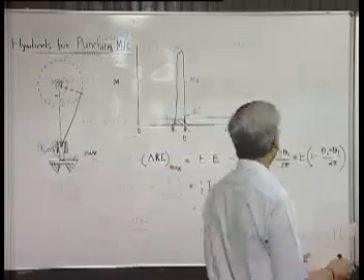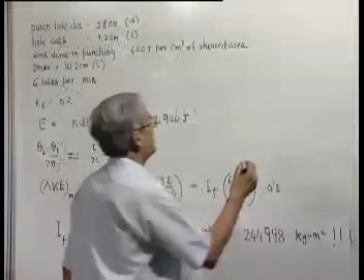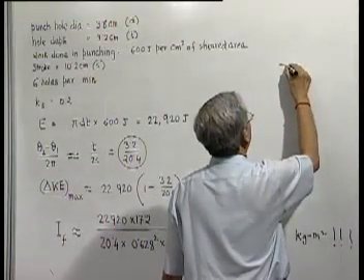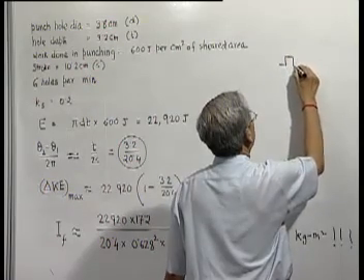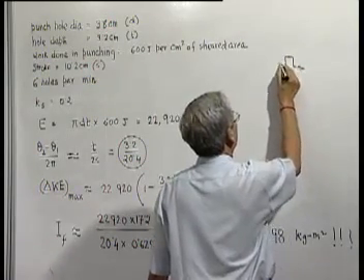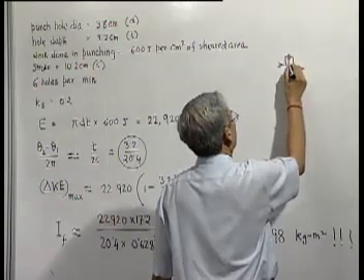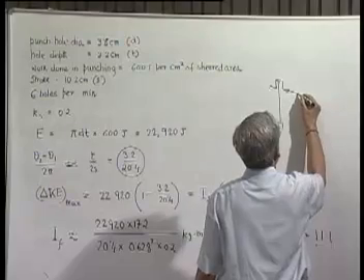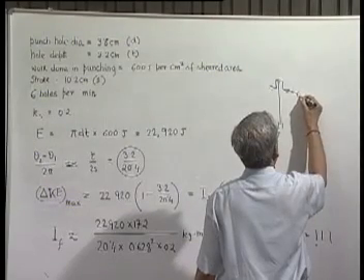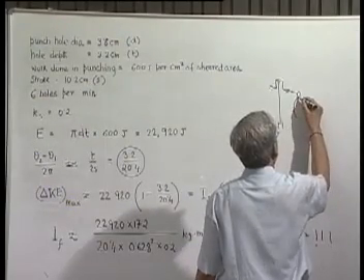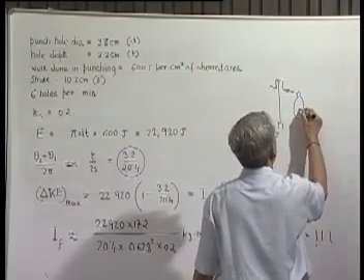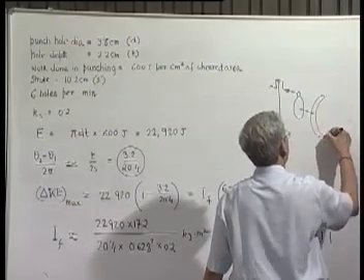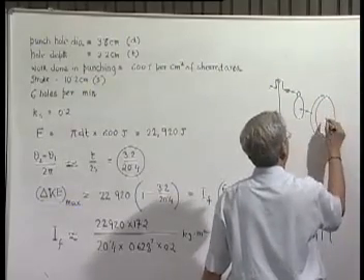Now this is solved in this manner: if we have this crankshaft and this is a punch, now rather than directly attaching the flywheel with this, we use a gearing system and we attach the flywheel on an idling shaft which is fixed.